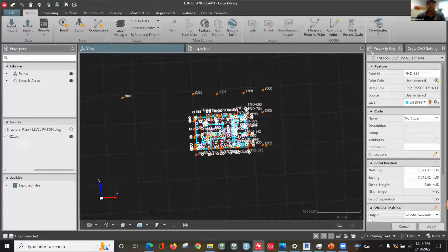When you bring in a DBX, you will go to Settings, Tools, Transfer User Objects. Make sure that from USB is selected. Pick the job, make sure the job is selected, and then hit transfer. What it will do is bring that over in whatever units you used in here, and whatever format, whether it's northing, easting, you did in here in Infinity, it will bring it directly in. So you don't have to worry about scaling.